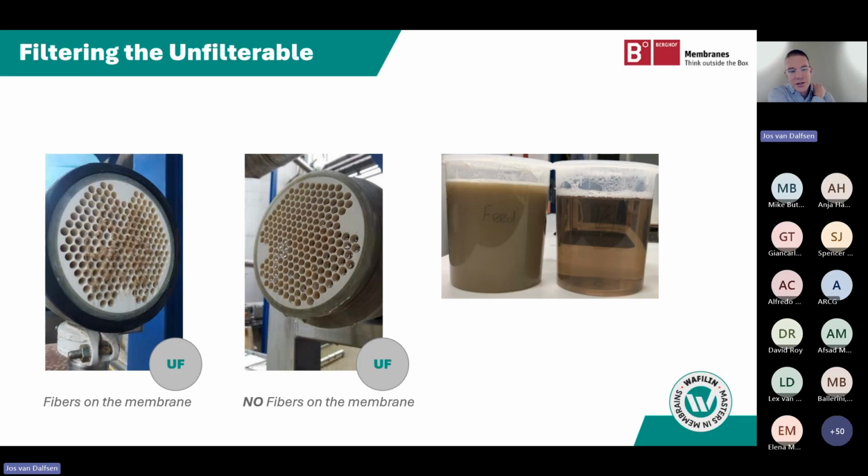And we changed the variations and the period of counterflow. We tried to optimize that in this pilot phase, but that also enabled us to design a stable process. And nowadays the units are running, I think, for 36 hours without a CIP interval. So quite an optimized process. Maybe a different CIP integration and also period than normally is done in MBR, but in food industries, the frequency of CIP is by definition a bit larger.